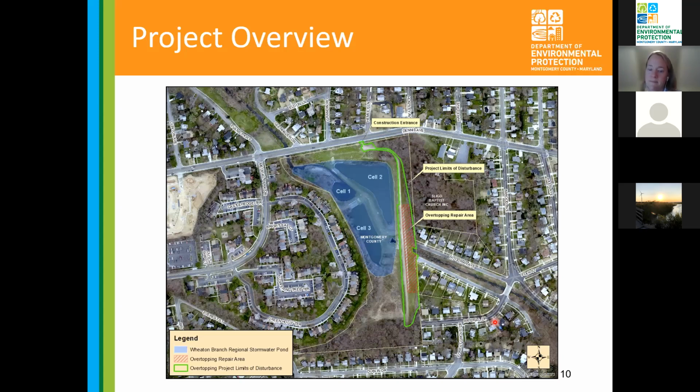And we came up with this articulated concrete block for its performance because this had been tested at Colorado State University, actually in the flume, where they placed these blocks and ran some very high flow over at different slopes, and these blocks provided the greatest degree of protection of all the options.